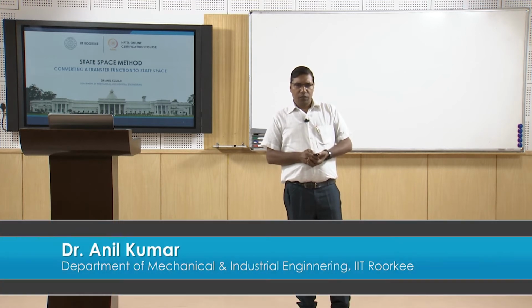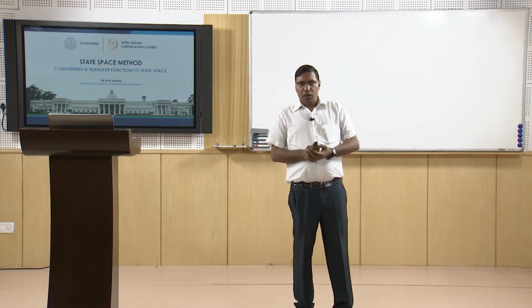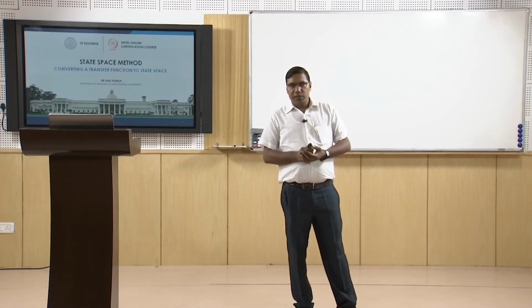So welcome to the state space method. In this lecture we will discuss how to convert a transfer function to state space. We have defined the transfer function in the frequency domain, and the state space approach belongs to the time domain. Now if we are given a transfer function, how can we convert this to state space?